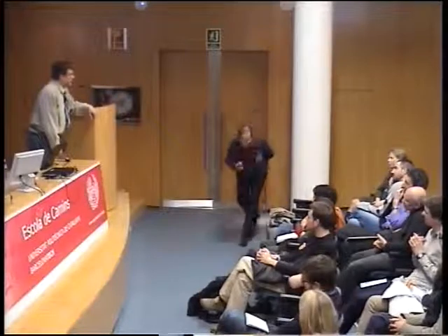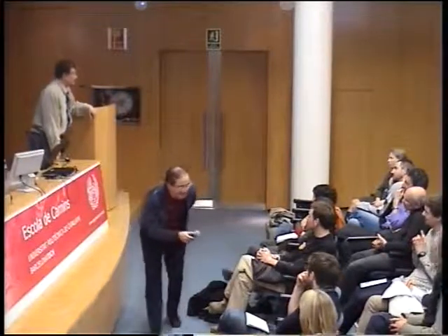And it's interesting that the deep sea in many ways is easier than rivers, because when you are taking seismic profiles or acoustic profiles of the bed of the ocean, you don't have to worry about a big tree floating straight at you to destroy your instrument. And especially big trees, as we saw below the Susquehanna Dam, love floods. I do have a number of colleagues who are trying to work around debris and severe velocity fields around bridge piers, to use the acoustic devices that have been developed for oceanographic applications to measure the development of scour holes. And there is now a lot of successful data on that.